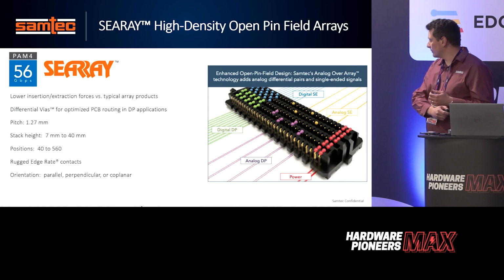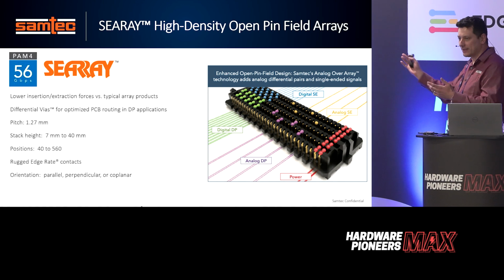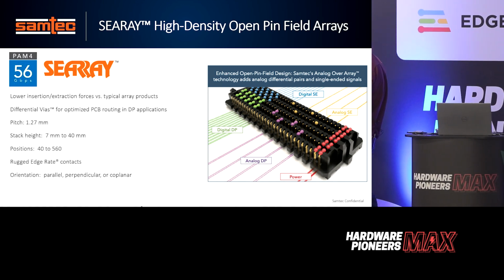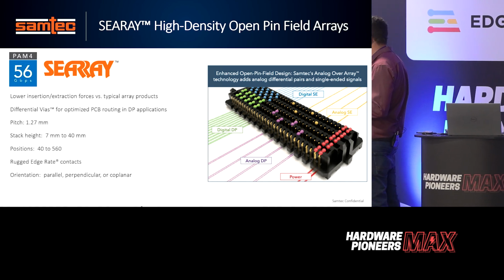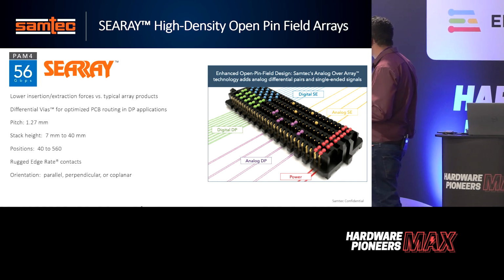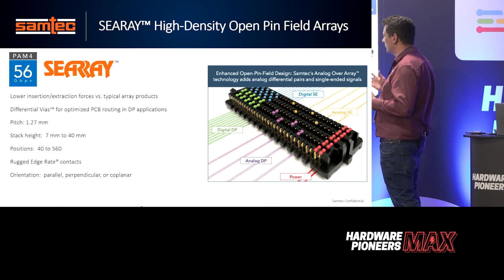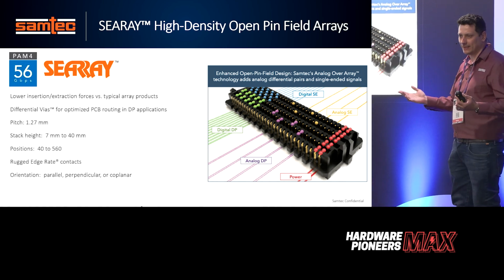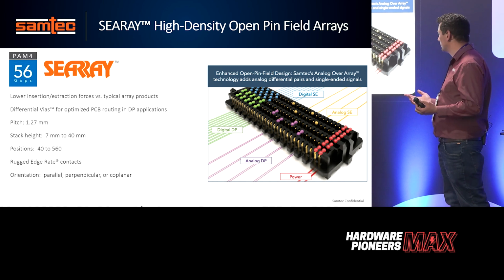So now, we look at the interesting part of FMC, which is the connector. The standard writes the Samtec SEARAY connector. It's a dual source, so there is a dual source available for this connector. But when we design this connector, it's what we call an open pin field array. So basically, you can define what you want to use the pins for.